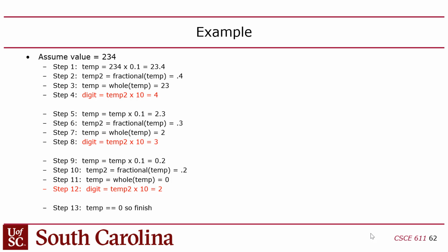Now you might say, wait a second, I got to do this 8 times though, 1 for each digit. Well, you don't really need to do it 8 times because if you put all the switches up, there's 18 switches. So if you put all the switches up as your input, that's going to be 2 to the 18th power minus 1, which is 262,143, which is only 6 digits, actually, not 8 digits, right? But do all 8 digits because in Lab 4, we're going to need all 8 digits, okay? But then you might say, what about, I don't have a loop. How do I do a loop? How do I loop through 8 digits? You can't. You're going to have to unroll your loop, meaning copy and paste the loop body 8 times, okay?